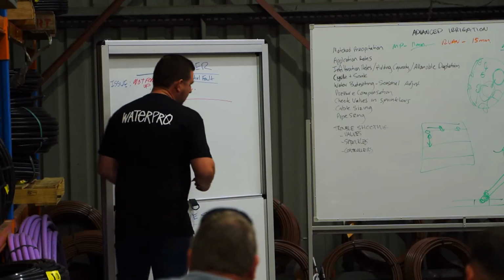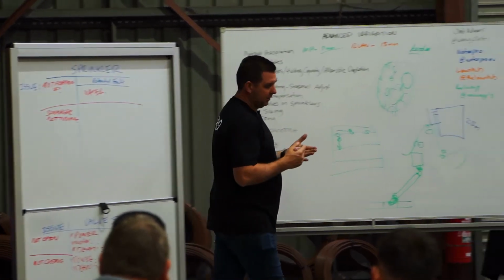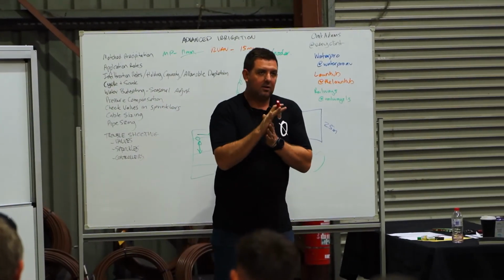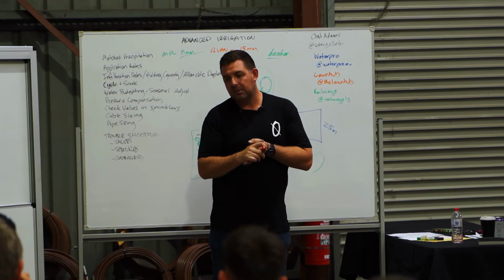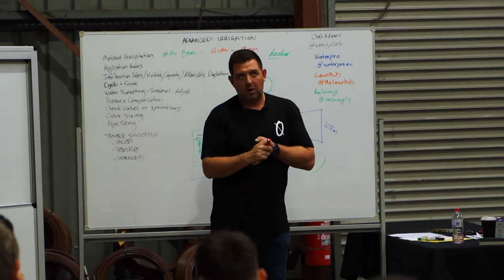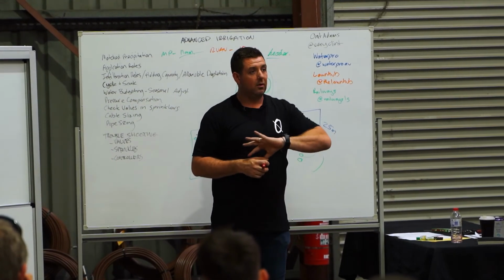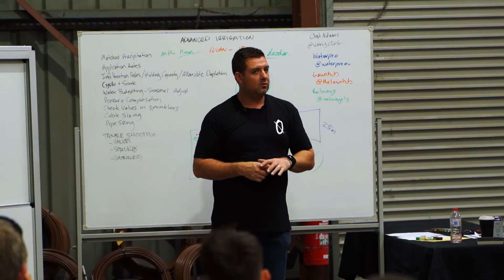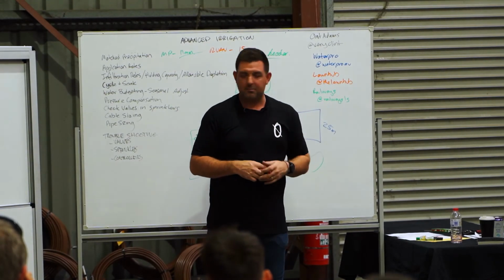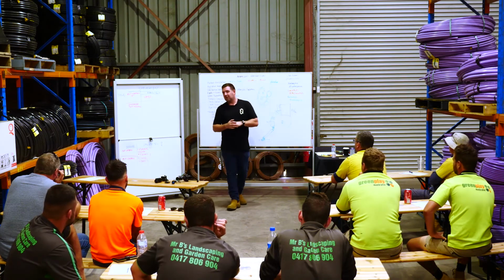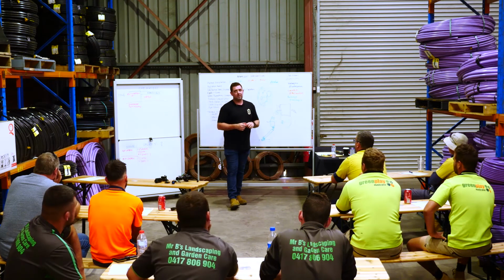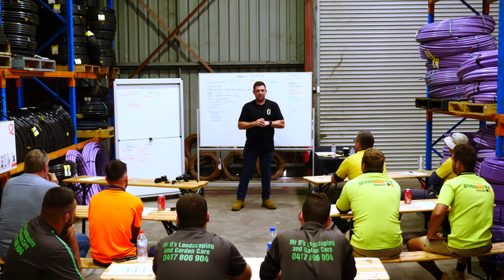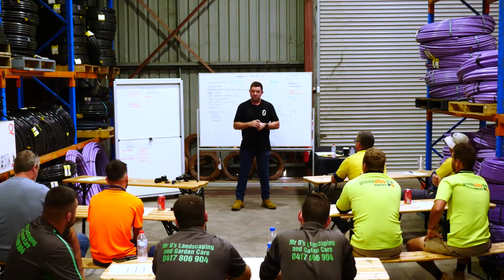So MP rotators, we've talked about that so many times already today. If they're dirty, they're not going to turn. It's not likely that too much pressure is going to stop a rotator from turning, but not enough pressure might stop a rotator from turning. It's probably not going to pop up to get to that point anyway. Gear drives, generally, if they stop turning, they're broken and they're not repairable, and that's a warranty situation.